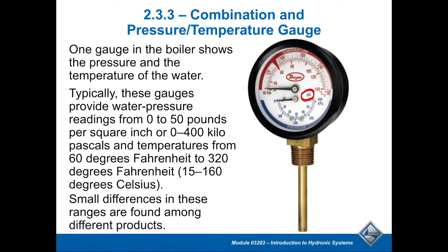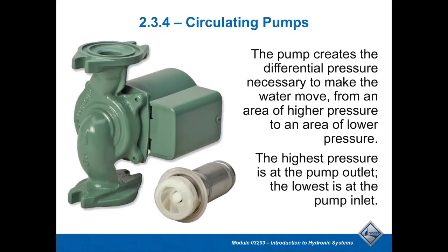The one thing I'd be real careful with on these types of systems is if you're relying on this as a very accurate way to measure the boiler pressure, be careful. A lot of these pressure temperature gauges, after a certain amount of time, the pressure gauge doesn't work very well, or the pressure setting becomes very inaccurate. So that's the one thing I would be careful on, if you're relying on that as your sole gauge. Most service technicians will have some other pressure gauge to verify the boiler pressure.